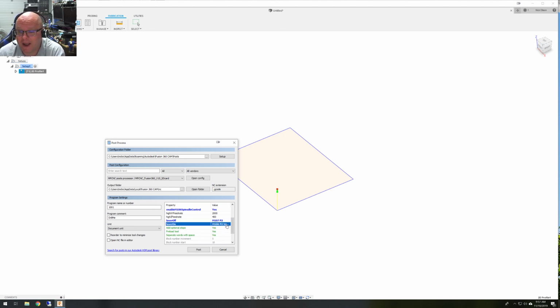And then this is where I pick my power. So I use S255. This was for my diode laser. I wouldn't do this for my CNC. I would burn it whatever it takes to get 10 milliamps. And for me, that's about 144. So I changed that to S144.